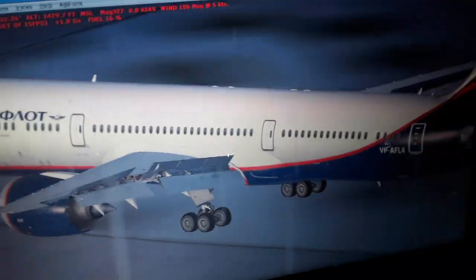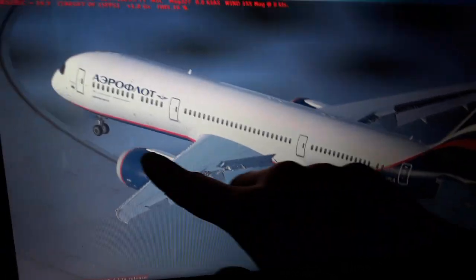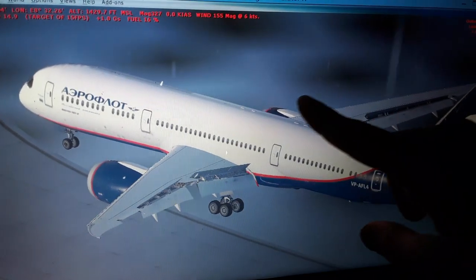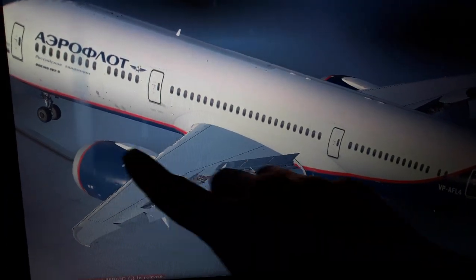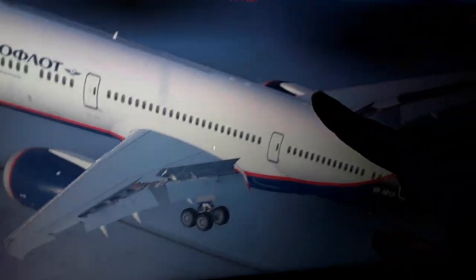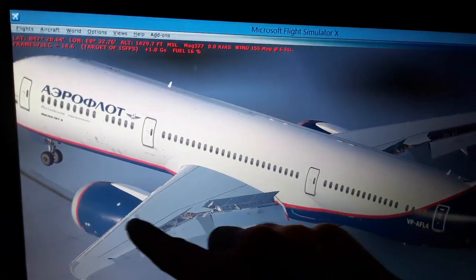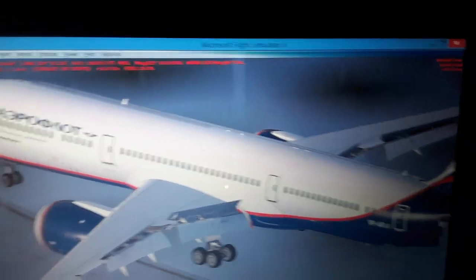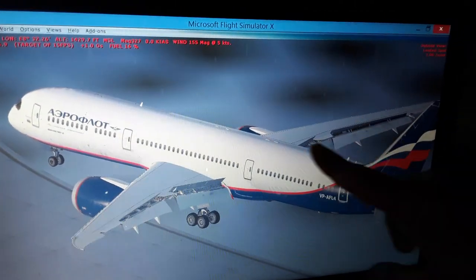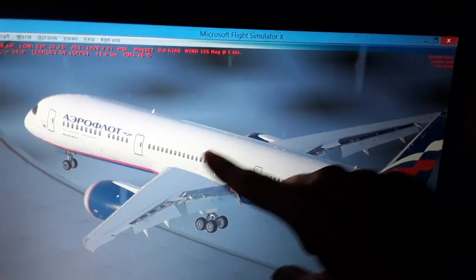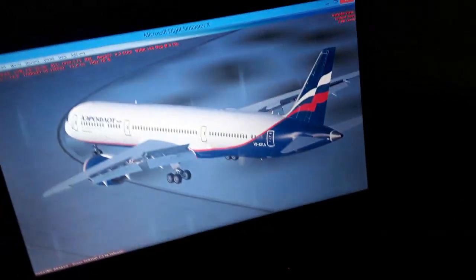So we have the thrust vectors over here that push the aircraft forward. Also we can see the fuel lines in the top surface over here. The fuel control, the wing and engine RDIs over here in the front. So we have the fuel tanks, the left wing tank, the right wing tank and the center tank. We have 30% right now in the left and right wing tanks, and 10% in the center tank. We have balance between the left and the right wing.